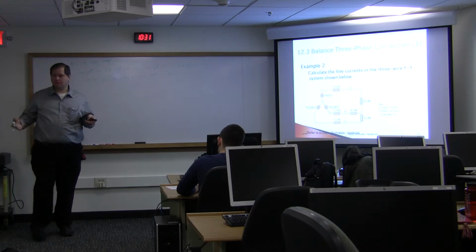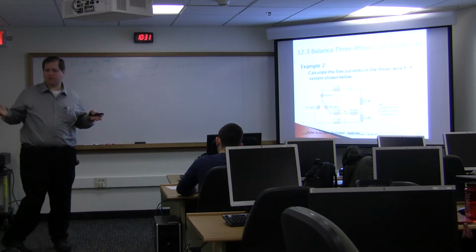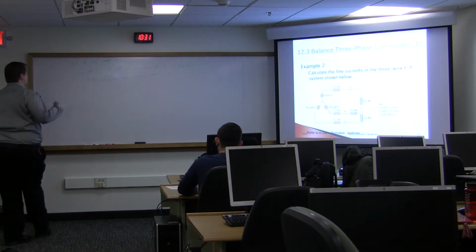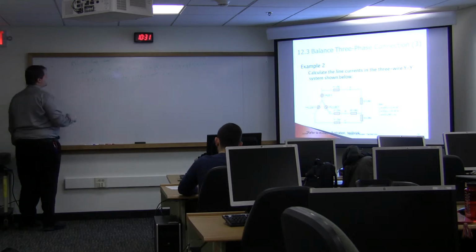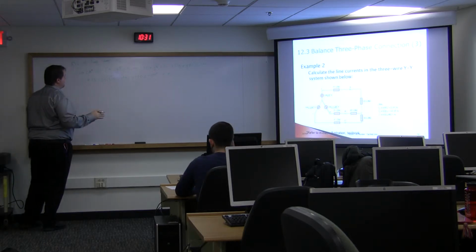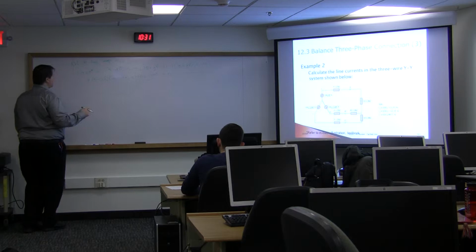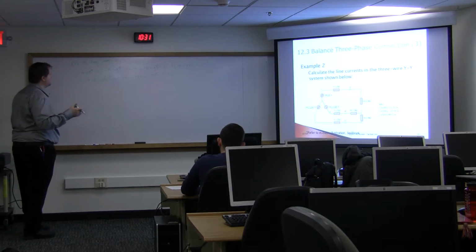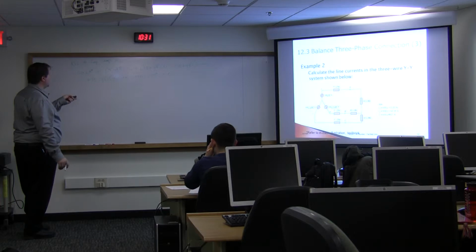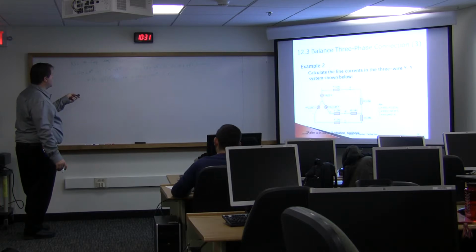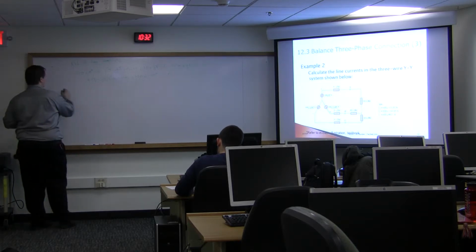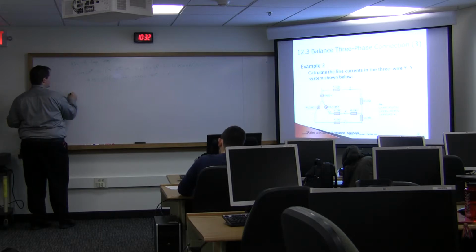So it's a little bit long, but it's just a KVL loop, right? And then I could write down my second equation, so I could simplify this and put all of my parts together. Again, I would use MATLAB to do most of this, but if we look at it, what am I going to have? Here I have a 10 plus J8 and another 10 plus J8, so I have times I1. So my I1 terms, I have 5 minus J2.